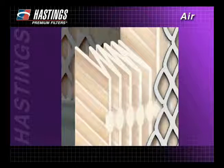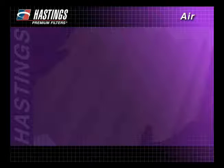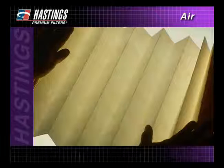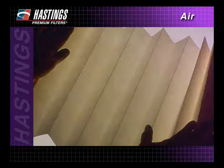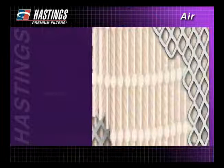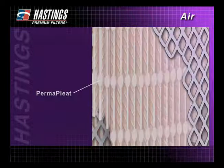As mentioned earlier, the paper media is the most important part of the air filter. Aside from selecting the proper media for each application, Hastings ensures maximum strength and minimum restriction on its heavy-duty filters through its PermaPleat design. PermaPleat is a special embossing process which creates built-in pleat spacing in the media. This adds extra stability and separation to prevent incoming air from causing pleats to bunch together.